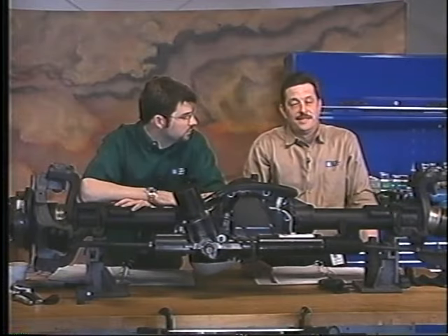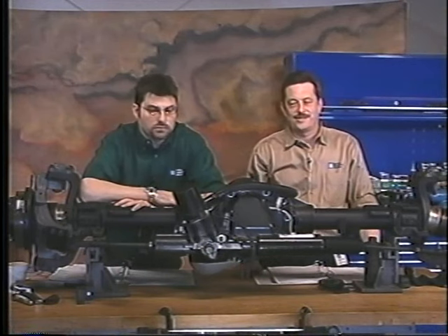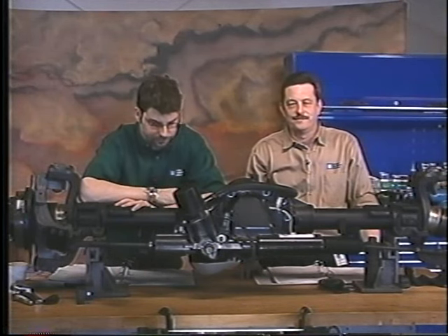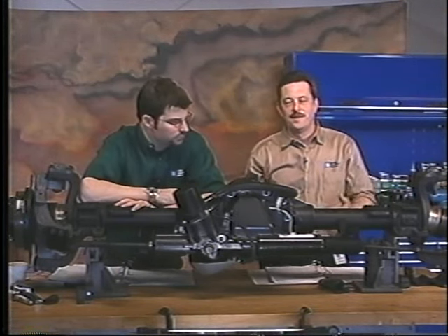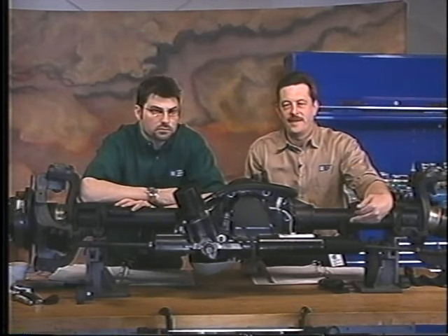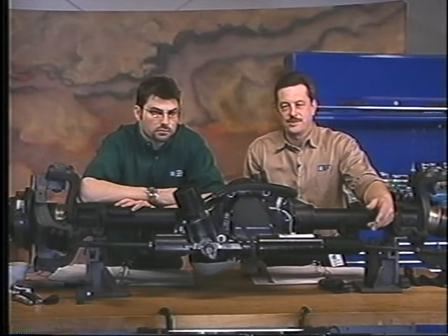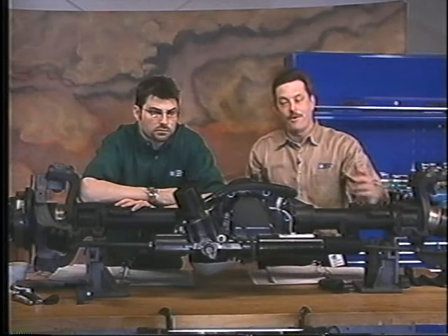If it's required, if the customer has to do it, then you've got to take on that responsibility and make sure we only have it in two-wheel steer. Got to keep it in two-wheel steer. That way we're not moving those rear wheels, and we're not going to cause that damage. If damage occurs, it's not a warrantable situation. Okay? All right. What about tire size? That's the other thing to really talk about. Don't change tire size on these vehicles. It's just not worth it. Too much going on there. We're dealing with the software in the module to deal with that. We're also looking at the PCM software and the ABS software. You've got to make all three of those match.